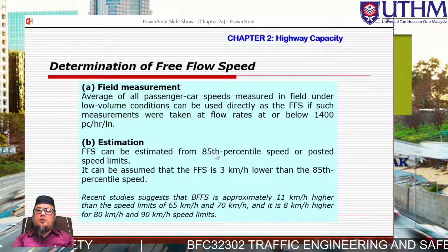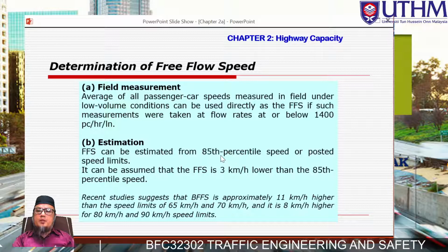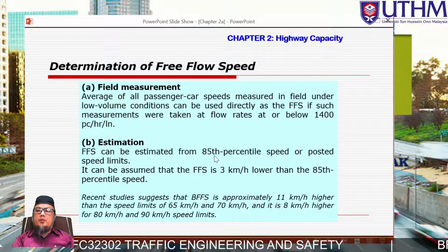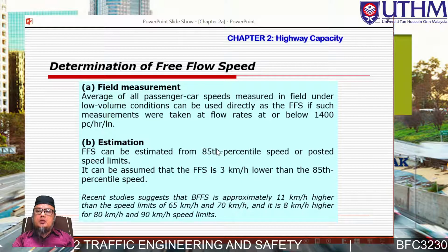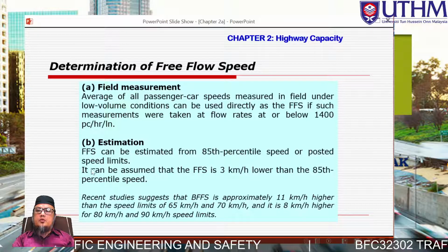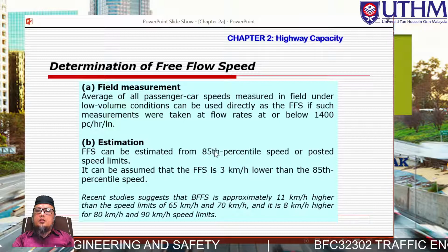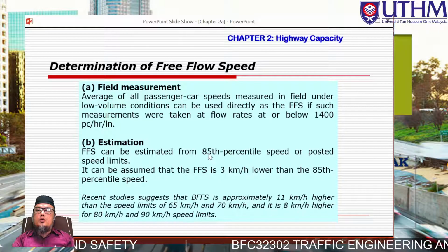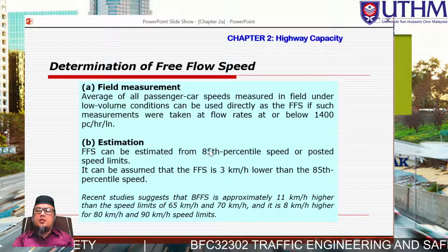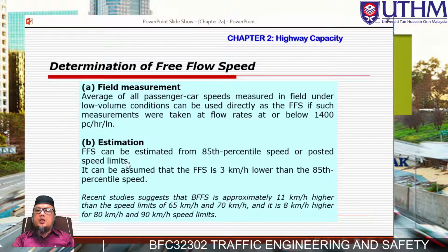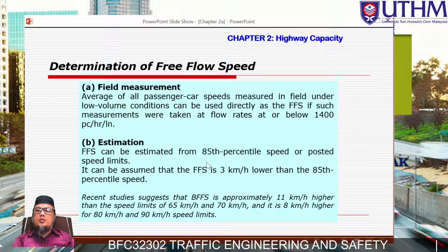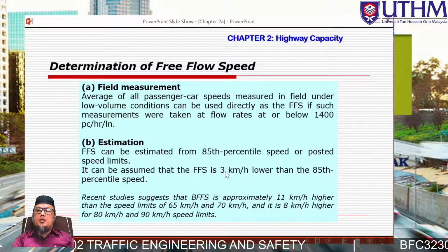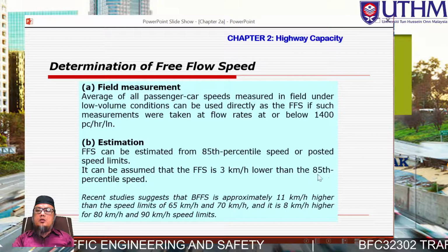First, we can assume from the 85th percentile speed from previous or related data. If we use the 85th percentile speed, we can also refer to the posted speed limit. Okay, let's take a look at this scenario first. For the 85th percentile speed, we have to go lower than this value. Let's say the 85th percentile speed is 90, so we can use a free flow speed or basic free flow speed of 87 because 90 is deducted by 3 km per hour. Okay, if we use the 85th...